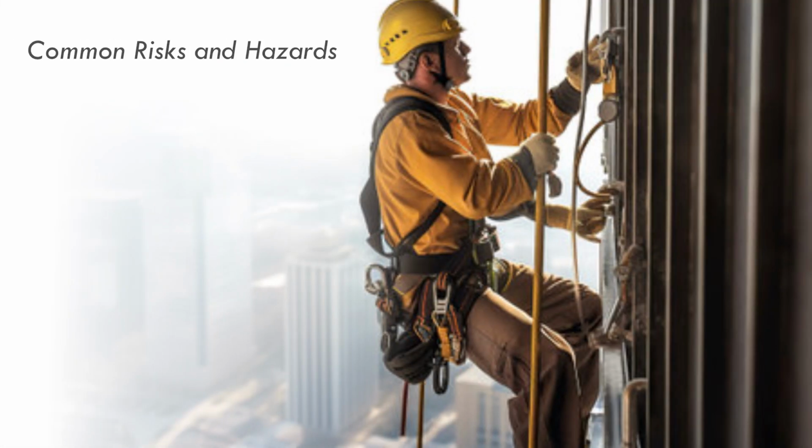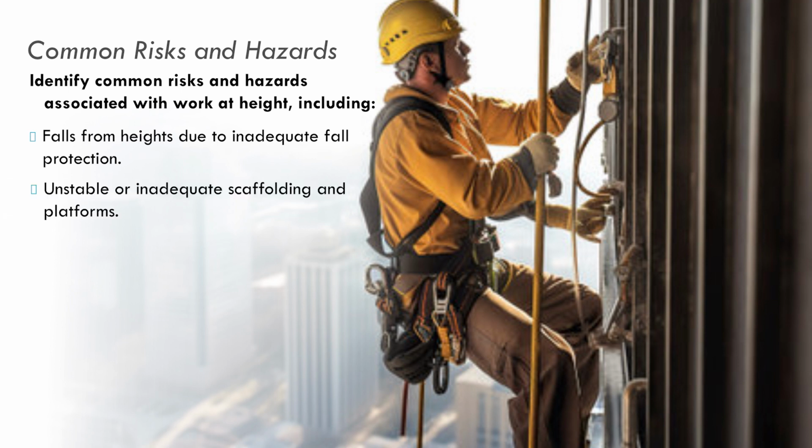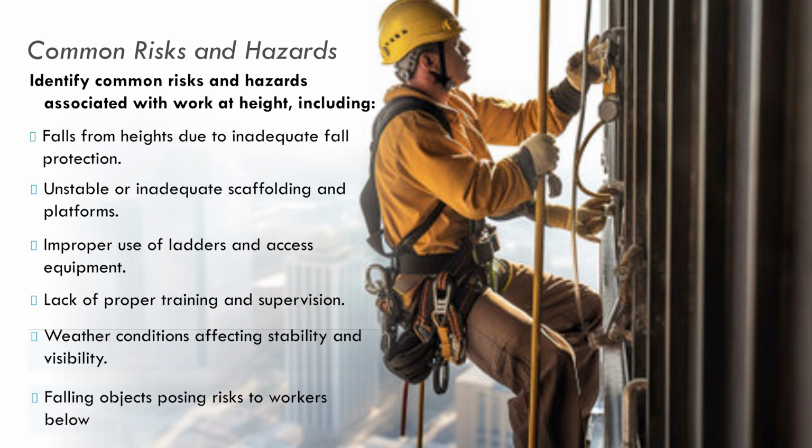Common risks and hazards. Identify common risks and hazards associated with working at heights, which include falls from height due to inadequate fall protection, unstable or inadequate scaffolding or platforms, improper use of ladders or access equipment, lack of proper training and supervision, weather conditions affecting stability or visibility, and falling objects posing risk to workers below.